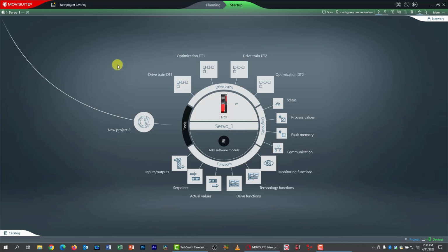Now, if you notice, if we go up here to the top left, it has the access name and that same code displayed there. If there's a fault or any kind of diagnostic symbols, they will appear there as well. So there's actually 2 places you can see it. We're not going to be able to check out any current faults because we have none, but we're going to go now look at the fault history just to see what faults this VFD has had in the past. To do this, we click the fault memory shortcut right here.